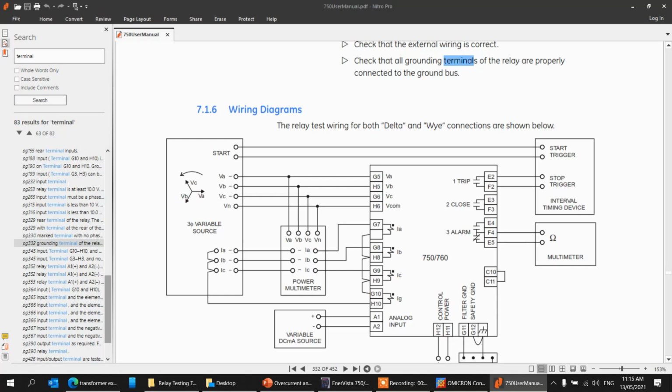Then we put our leads there from the Omicron and the other lead to sense to the earth. Once the relay trips, that contact will close, and you will have voltage flowing to your Omicron. Then it will stop the time. So again, as Jonelle is saying, it's a little bit tricky, but if you are really good at analyzing controls and everything, then you go that way.